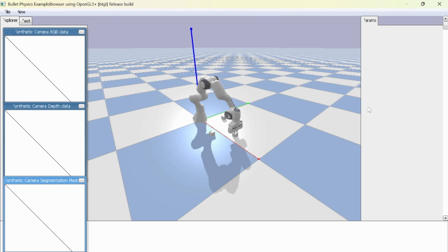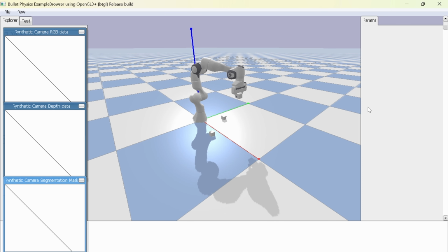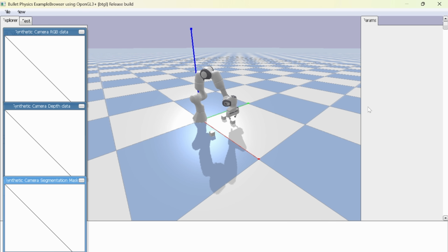In this project, I programmed the Panda arm to perform a classic robotics task called pick and place. First, it moves its arm above a cube, lowers the gripper, closes around the cube, lifts it, moves to a new location, and places it down. To make this work properly, we had to solve several technical challenges like improving smooth motion and stabilizing objects. I stabilized the cubes so they would not shake while being carried, and created a loop to process multiple cubes automatically.